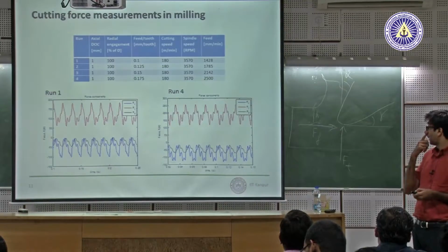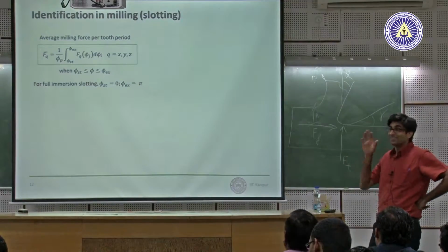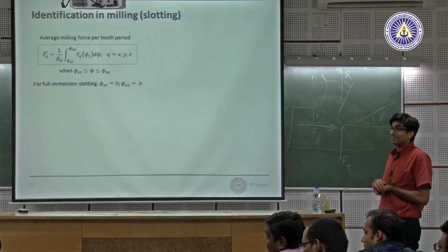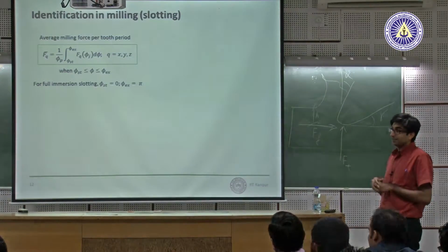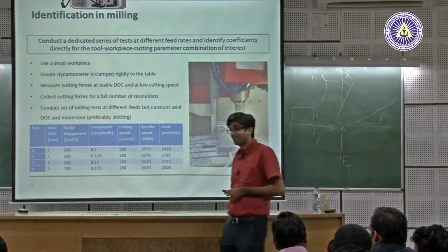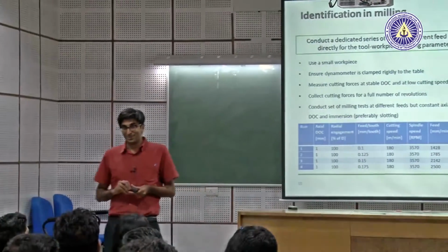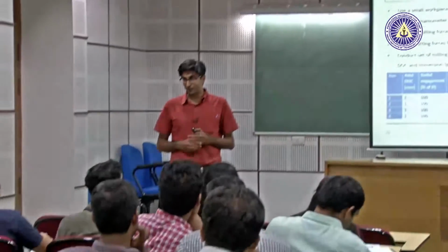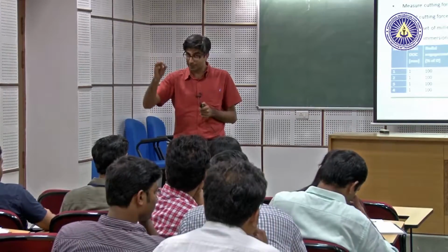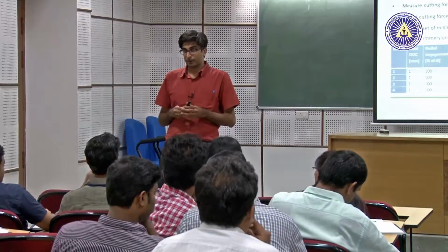Okay, all right. You have a question? There is a Kistler dynamometer which gives an average value. No. If the dynamometer is giving you an average value, we are not using the dynamometer correctly. Dynamometer gives you instantaneous force value. If it's giving you an average, that means it has inside it something that can calculate an average.